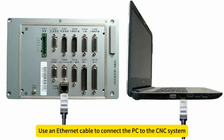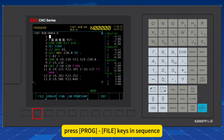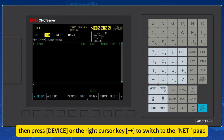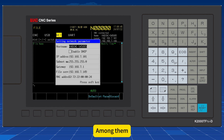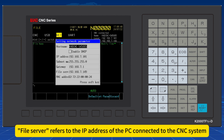Use an Ethernet cable to connect the PC to the CNC system. On the CNC system side, press PROG, file keys in sequence, then press device or the right cursor key to switch to the net page, and press the right extension key, param, to enter the setting network parameter page, where you can see the CNC system default network communication parameters. Among them, IP address refers to the IP address of the CNC system. File server refers to the IP address of the PC connected to the CNC system.